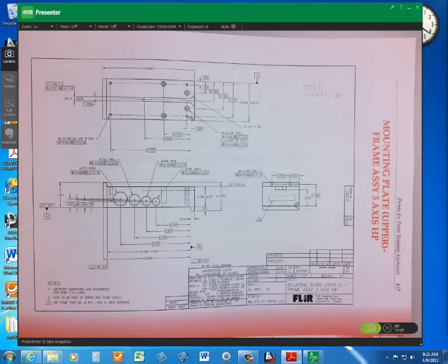So they doubled it. They knew what position they needed for controlling the position of the part, and they just doubled it for the counterbore, just for good measure. That's still pretty tight. 14/1000 is 1/1000th of an inch less than a 1/64th of an inch, and counterbores kind of run on 64ths. So the critical thing here is the position of the hole.